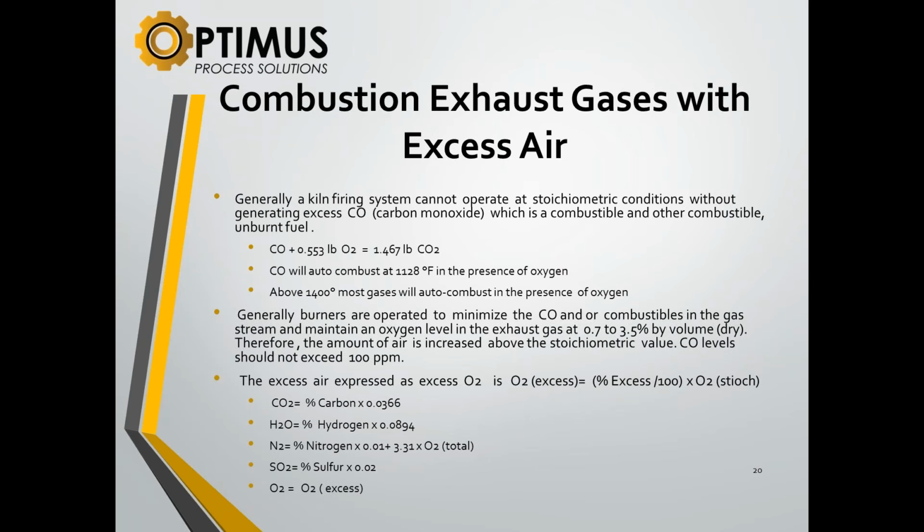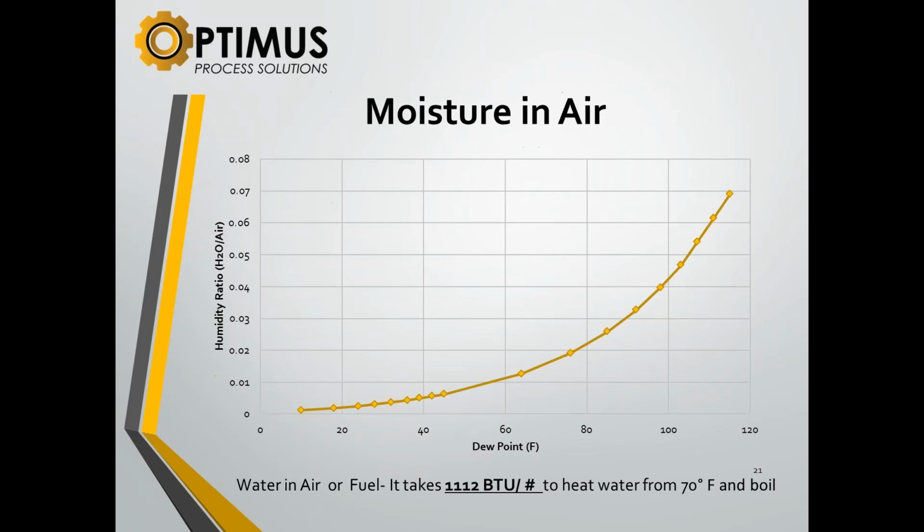Another thing I think we covered, on a humid day, the amount of water in the air can be significant. So any of that, you got to take that into account. Right. So Louisiana versus Arizona. Right. You could be heating an extra 5-6 million BTUs. Right.